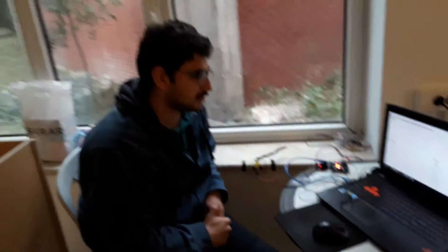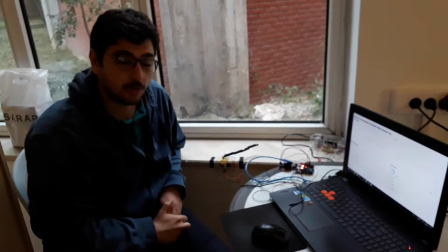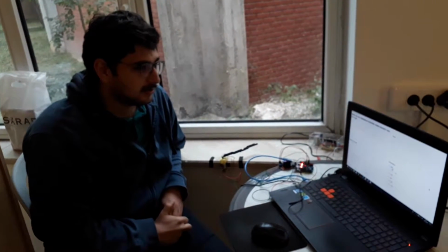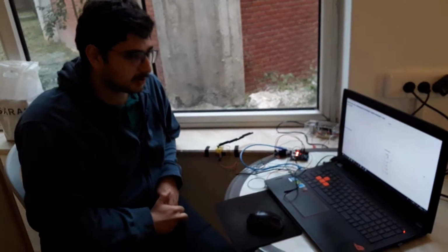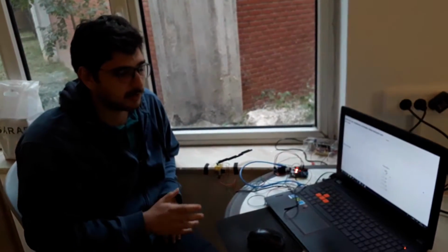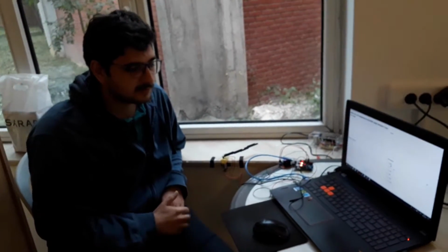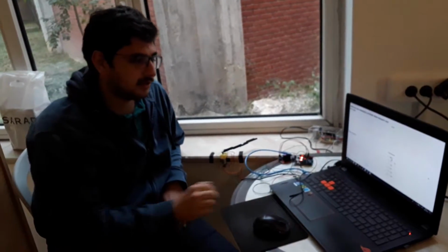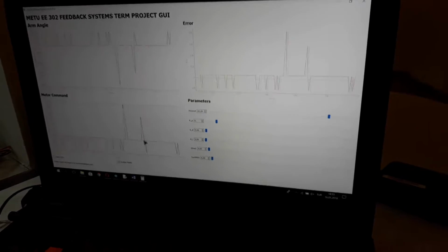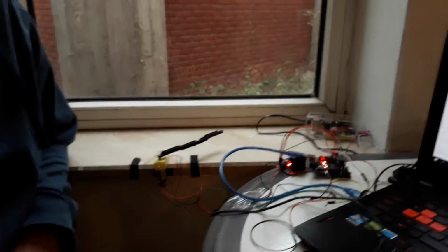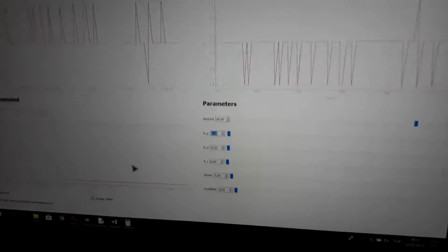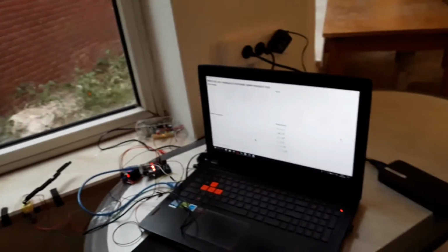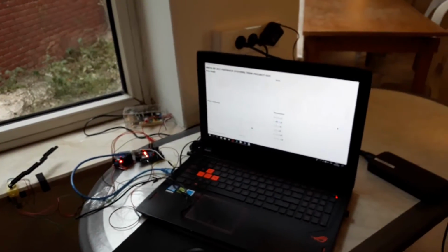If we want to observe the overdamped case, experimentally we couldn't observe it because the Kp value is about 0.1719, and in this case our system does not work because of the friction of the motor, and I set it to 0.19, but there is no motion and there is no noise. There is a problem in our system because of the motor non-idealities.